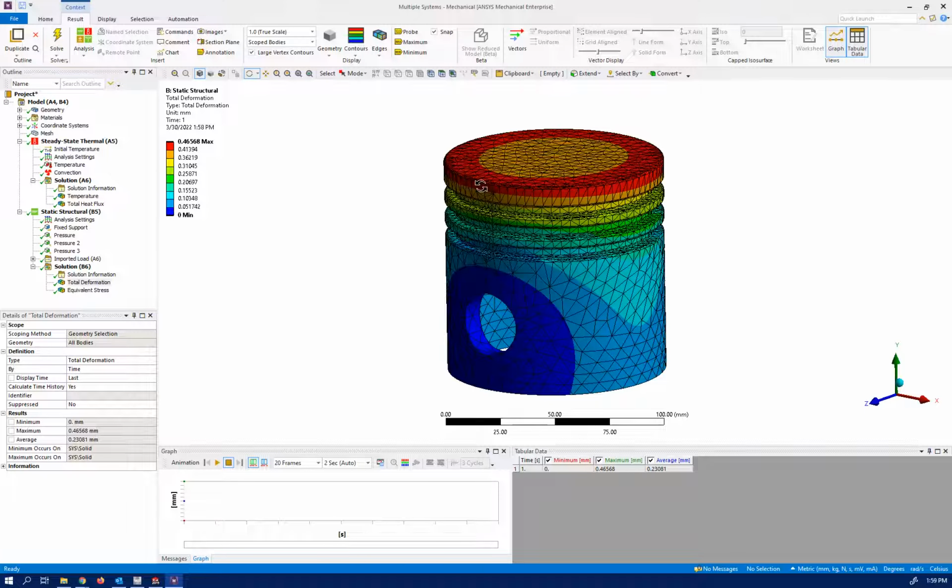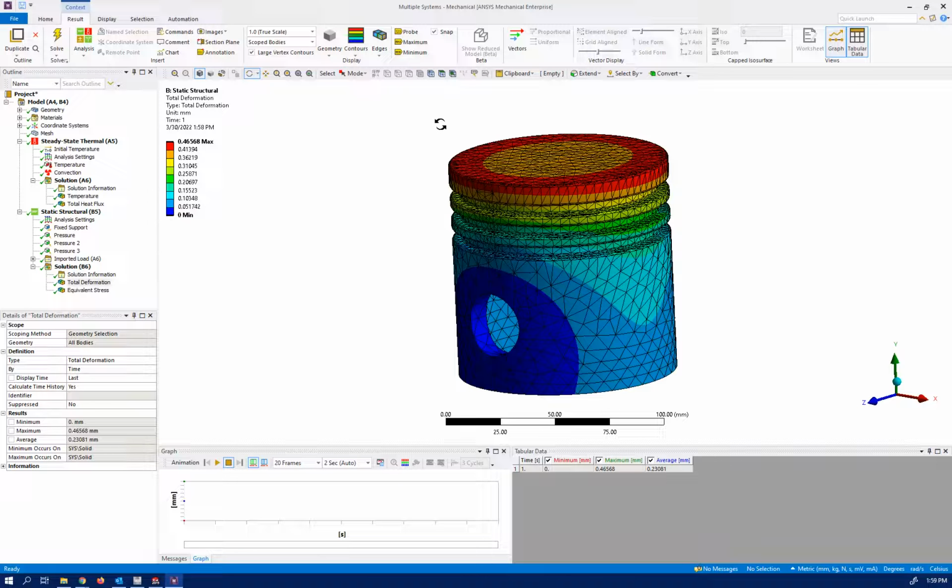It's like a ring here, and that is why when they manufacture these pistons, this upper surface, the outer part, must be very strong, resistant to temperature and friction, because it's going to increase and expand a little bit, so it's going to have some friction with the side. So this upper part is very important. That is why when we have a damaged piston, usually this area is the damaged area.